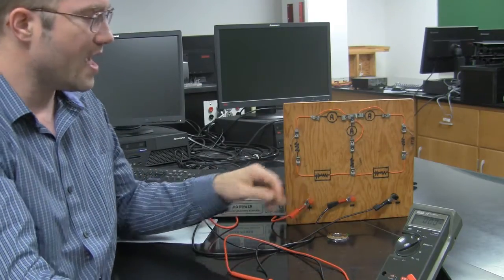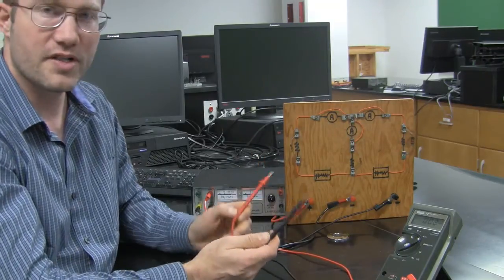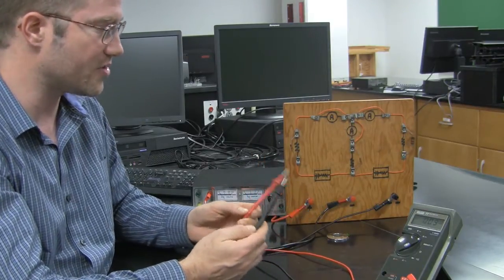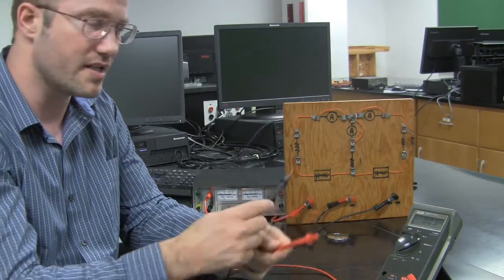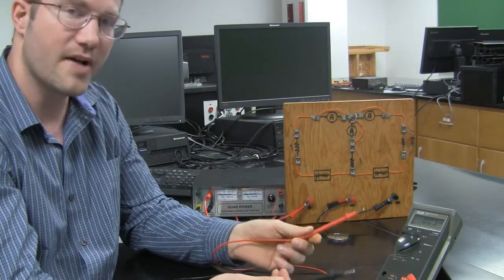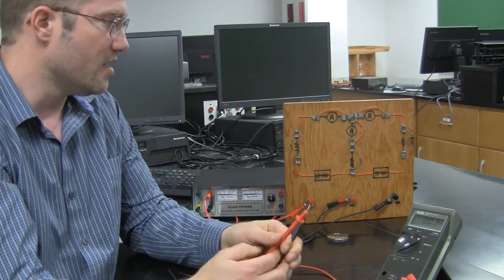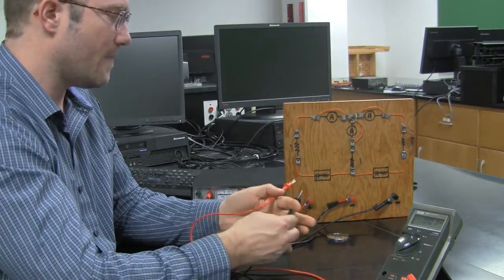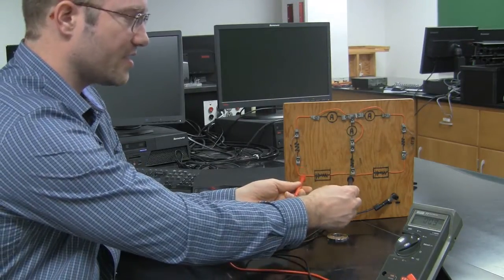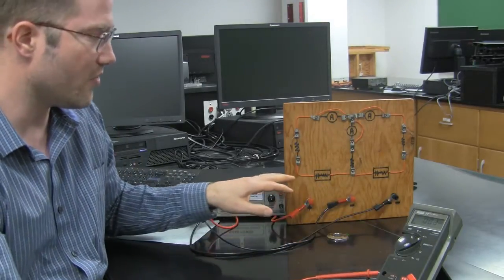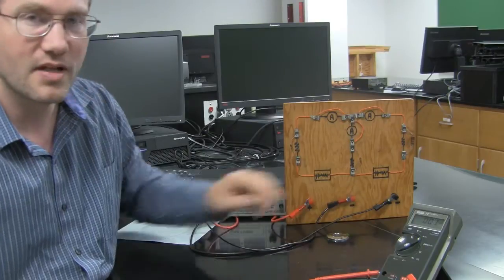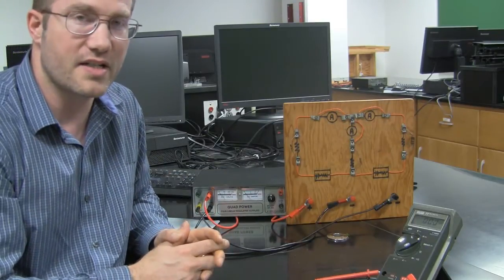All right, so I do that with both, and I get a voltage measurement. And be sure that you're consistent with your leads, because if you turn these around, you'll get a negative instead of a positive, or a positive instead of a negative. So let's read our voltages right to left like this. Now, once you've got your voltages, V1 and V2, then that's two more unknowns that are taken care of.